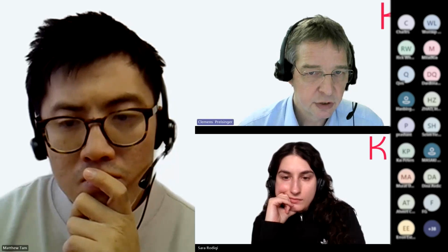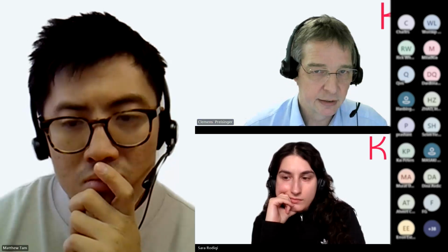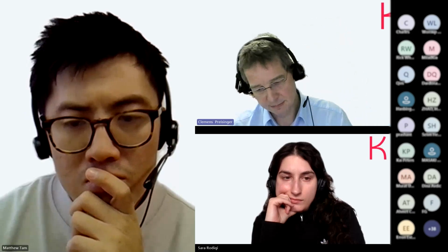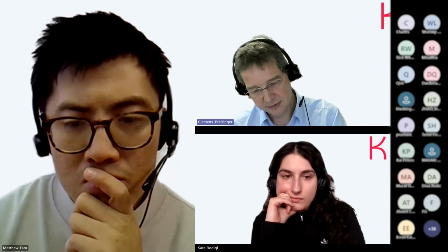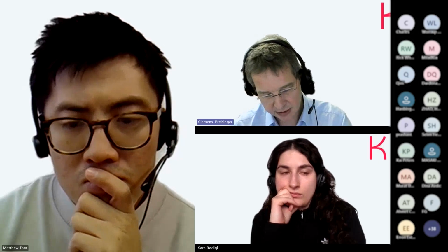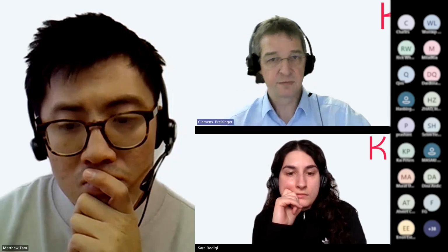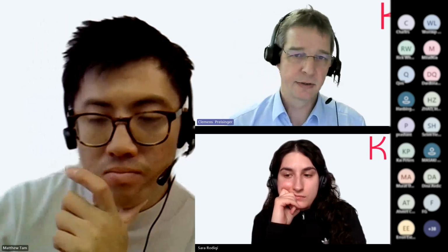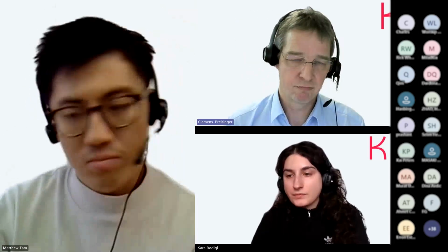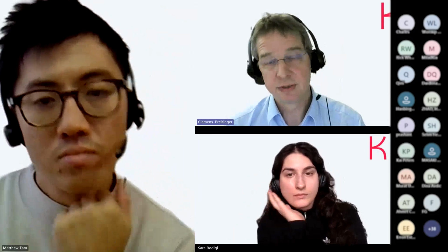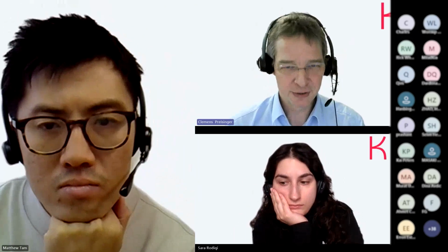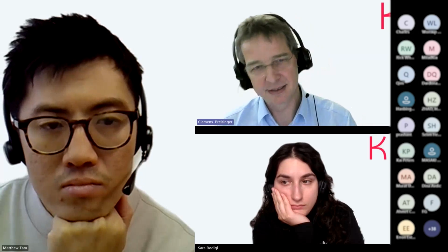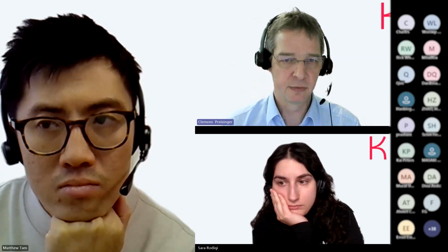Oh, large deformation analysis. This is a nonlinear work in progress. It contains three methods: dynamic relaxation, arc length method, and Newton-Raphson iteration for dealing with the geometric nonlinearity. However, it's not yet in a state where it works all the time, let's put it that way. So if it converges, then you get correct results, but in many cases it doesn't. It's still something which needs to be improved.